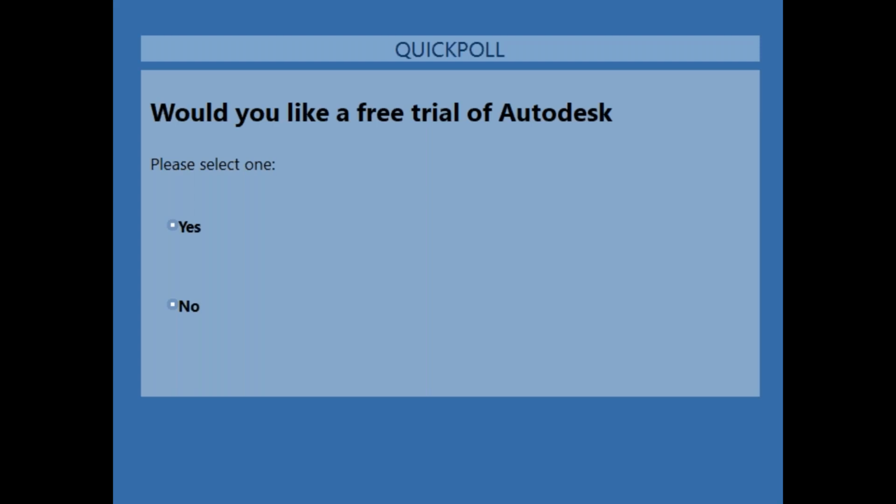Here's a good question. Strictly in regards to 3D takeoffs, can you elaborate on how Autodesk Takeoff is better to use than Assemble? So I'd say Autodesk Takeoff is not necessarily better at 3D takeoffs than Assemble. It's just more unified to our other offerings such as Autodesk Build, Autodesk Docs, and BIM Collaborate. And then also it has a model conditioning component, so you can add parameters on top of model objects. But it's not necessarily better or worse. It's just a different workflow. And of course, Takeoff allows you to do 2D takeoffs, which Assemble does not allow you to do.